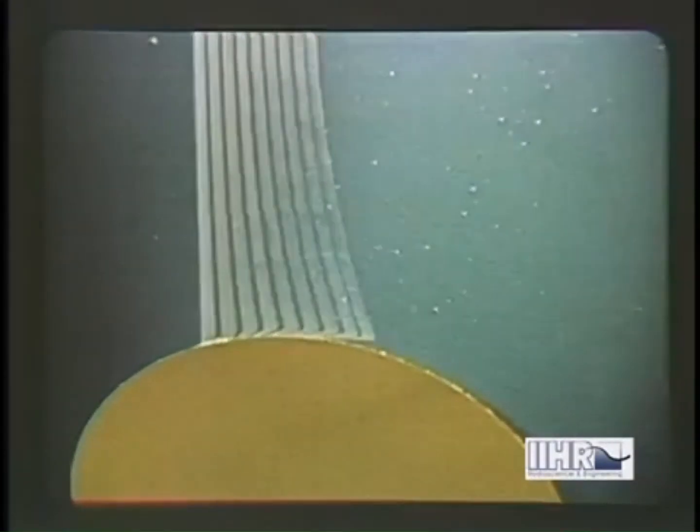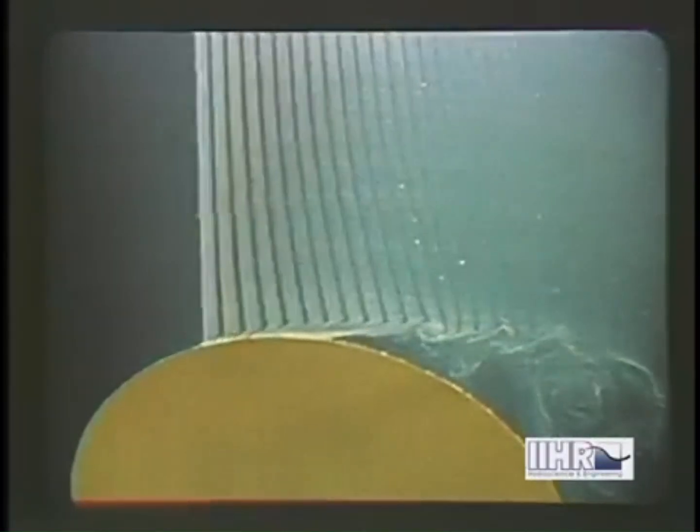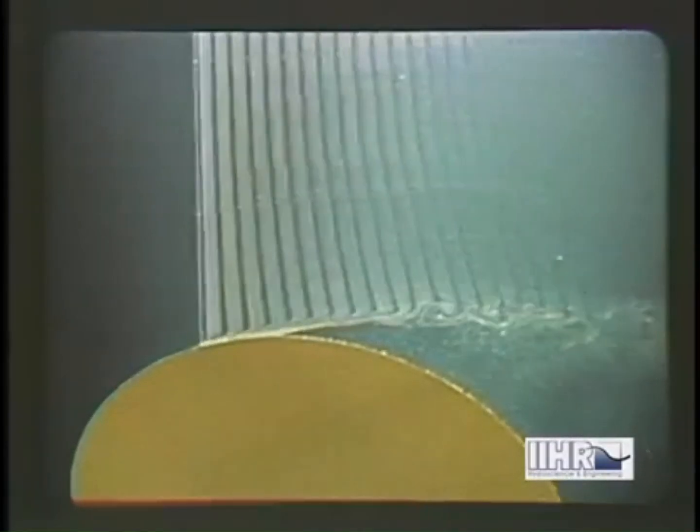As the boundary layer develops around any body of appreciable curvature, the point of separation rapidly moves forward from the zone of maximum pressure rise at the rear to the zone where deceleration first occurs. As a matter of fact, no change in boundary alignment is really necessary, just so long as there is a shear zone of low velocity and an adverse pressure gradient, such as prevails beneath the front of this undulous surge, moving slowly against the flow.